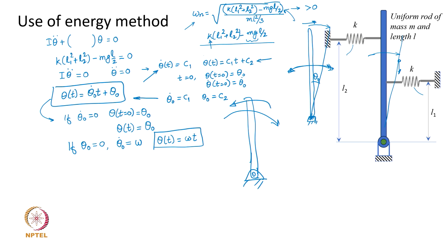which is the condition that we always relate to in a simple vibratory system, that there is a continuous interchange between the kinetic energy and potential energy. The mass travels back and forth continuously, moving about its mean equilibrium position. For this case, the mean equilibrium position assumed was the vertical position. So, this is a case of a system that is getting unstable. It is not reverting to its original equilibrium position. So, the motion continuously grows with time.